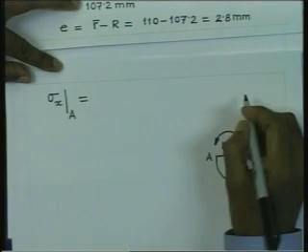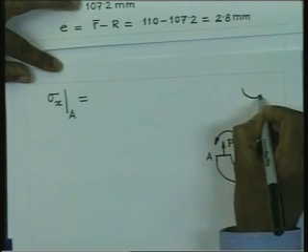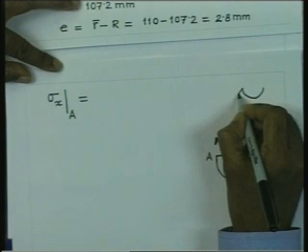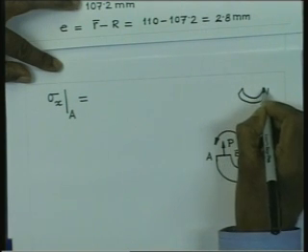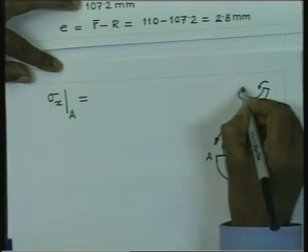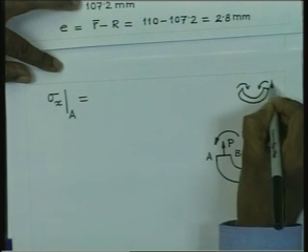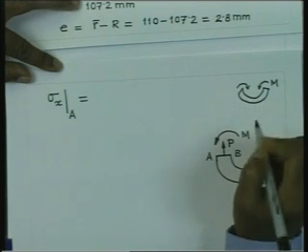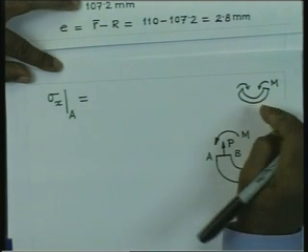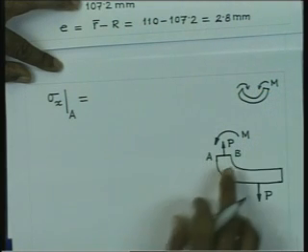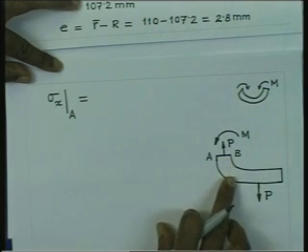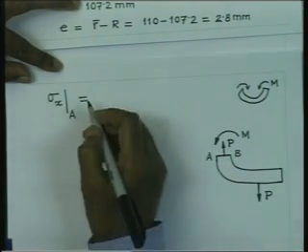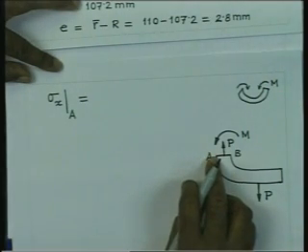The bending moment that we considered to be positive was like this. That was our curved member; we applied the bending moment like this. This bending moment is considered positive, and it increases the curvature of the beam, or reduces the radius of curvature of the beam. But in this case, this moment is going to increase the radius of curvature, and hence it is a negative bending moment, and therefore the stress here is going to be